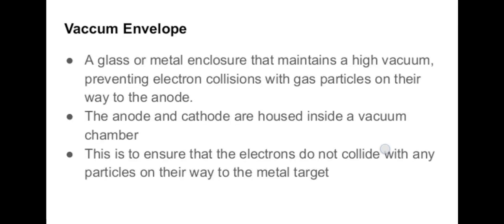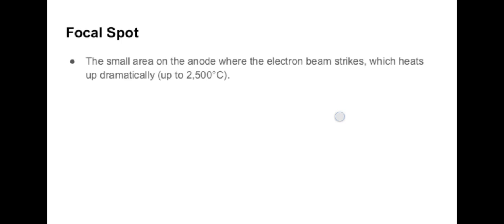Then next is about bearings. Usually the anode assembly will be rotated with the help of bearings which are made up of steel ball races. The bearings are in the high vacuum environment and will require special heat insensitive non-volatile lubricants. Usually the bearings are coated with lead or silver, which acts as a lubricant. Commonly used lubricants such as oil and grease will not be used in these setups since they will vaporize during heating and destroy the vacuum.